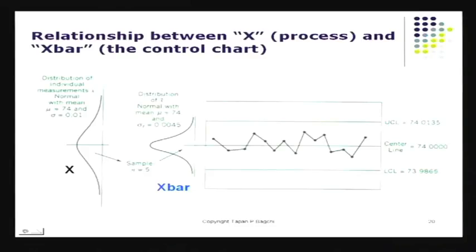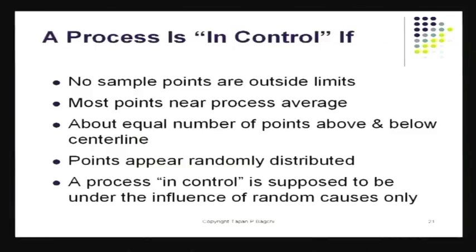Control limits actually have nothing to do with specification limits. Control limits are calculated based on the data that you have, and some constants, some multipliers. But basically control limits are calculated using the data that you've collected when the process is in control, when there are no wide variations. That we'll see again when we get into the calculation of control charts and the control limits.